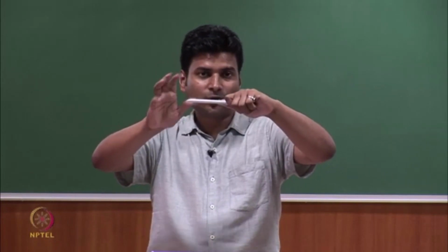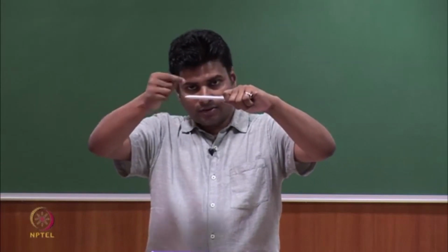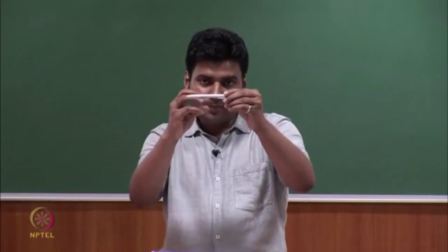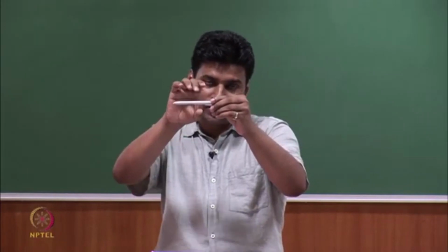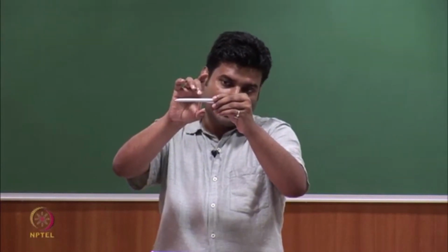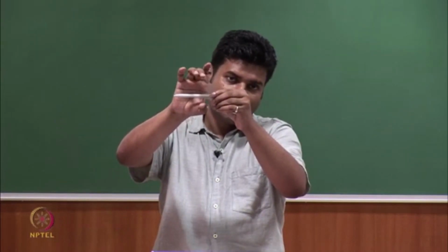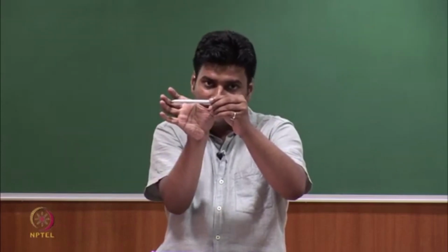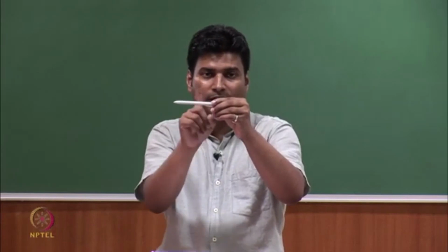It turns out if it is an isotropic cylinder and you are stretching it, then the points do not change their theta coordinate. Similarly, if you pressurize it from within, you are trying to change the radius of the cross section, and then due to Poisson's effect there will be axial shrinkage, because pressure is not a direct thing.